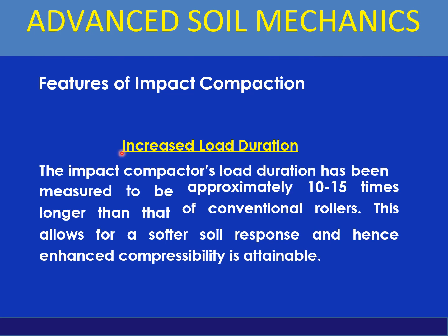Then comes increased load duration. The impact compactor's load duration has been measured to be approximately 10 to 15 times longer than that of a conventional roller. This allows for a softer soil response, and hence enhanced compressibility is attainable.